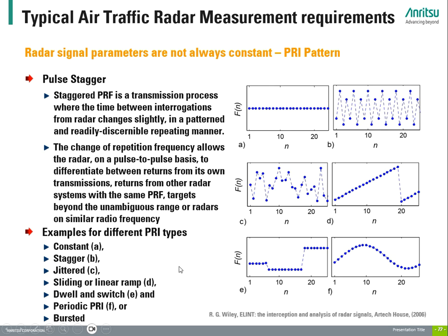The topic of PRF is a long one and we don't go deeper here. Just keep in mind that other PRF or PRI types also exist. Radar signal analysis, especially on the background of electronic intelligence, ELINT, allows us to identify based on the PRF pattern the type of radar, its application, or even its fingerprint. A fighter radar, or a marine radar, or an ATC behaves differently.